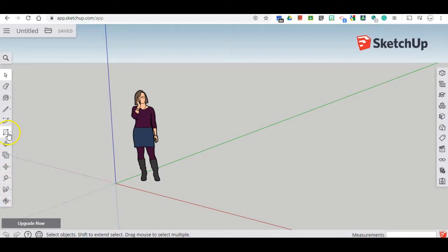Okay, so let's start with the rectangle tool. We click on that, click on just the regular rectangle, and you see a pencil with a rectangle. Okay, if you move it to the origin, it'll snap to it. Okay, so let's move our mouse over here. We're going to tap on the mouse pad once, and it's going to lock it into that corner.